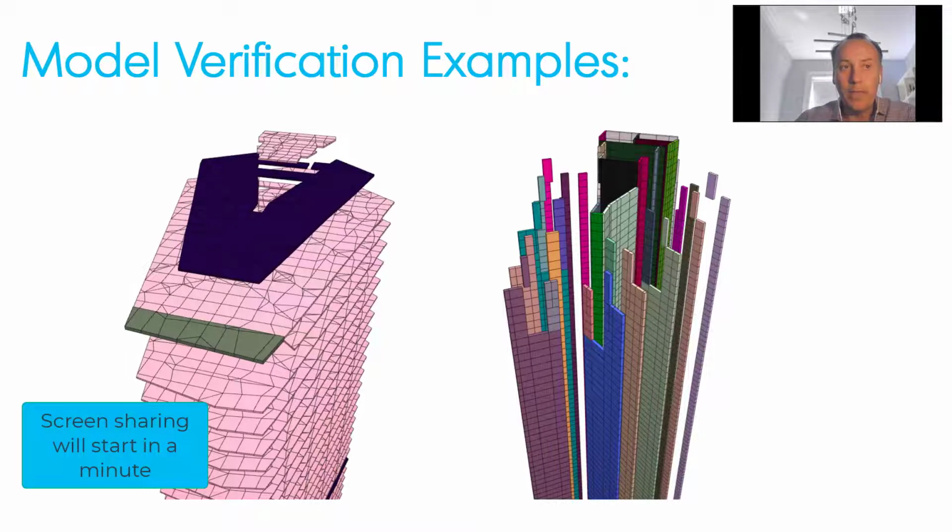So all that individual would have to do is go to File, Export, E2K. So now I can go ahead and actually save the E2K file. I'm going to set the units and we're done. So in this case, we've now created this file right here, which is an E2K file. All of the subsequent models that we open up will have already been converted to E2K, but I just want to highlight the fact that that's your starting point.